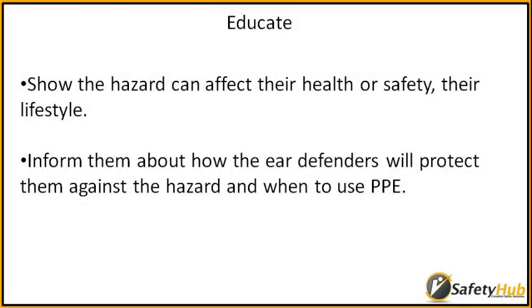We want to educate employees about the noise hazard and make it personal to them: how the hazard can affect their health or safety, their lifestyle. Inform them about air defenders, how they will protect them against the hazard, and when to use the PPE. It's really important that when you're talking to them, you talk in their language, whatever language that may be.